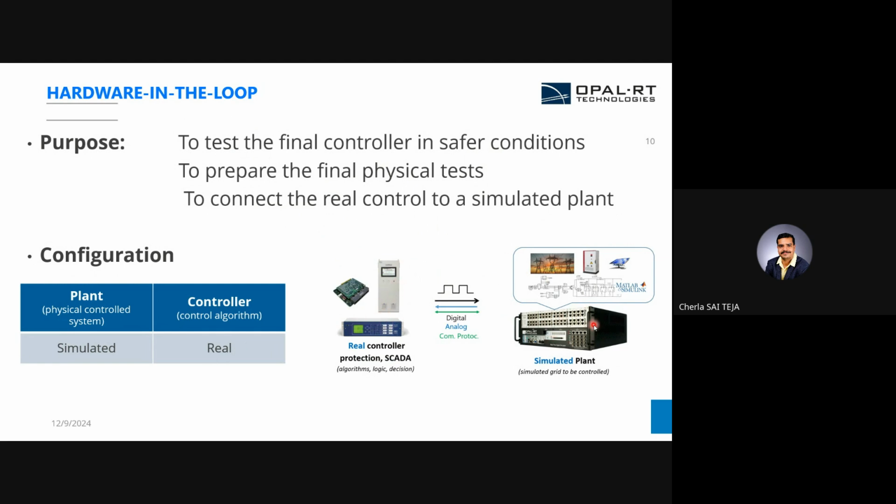Here we apply different kinds of faults on the simulated plant and see the controller response: whether the controller is able to detect the faulty cases of the plant and take the right decision or not. We test that in this hardware in loop testing.